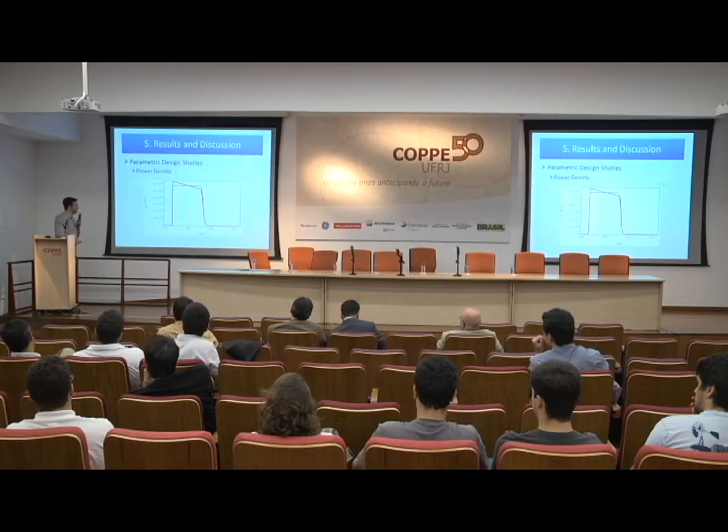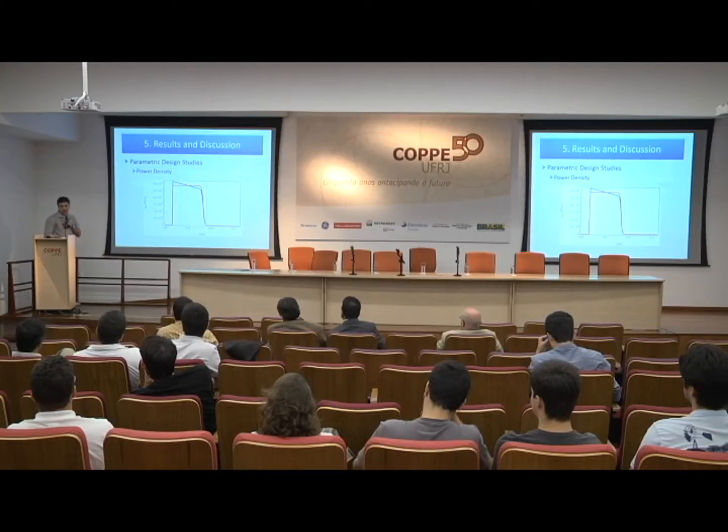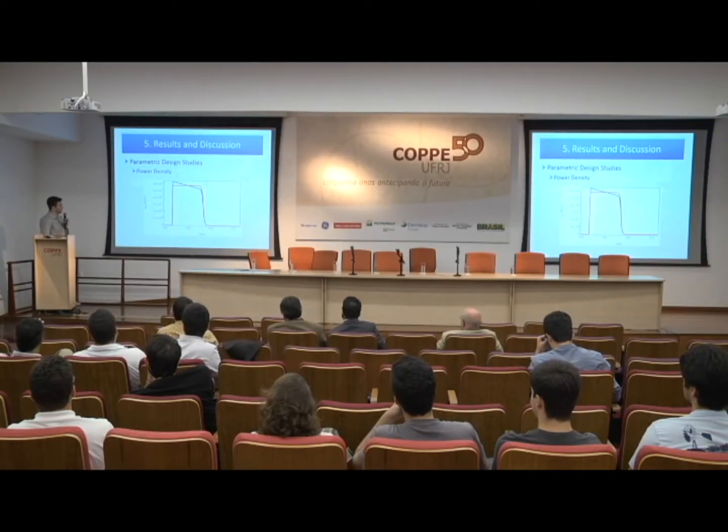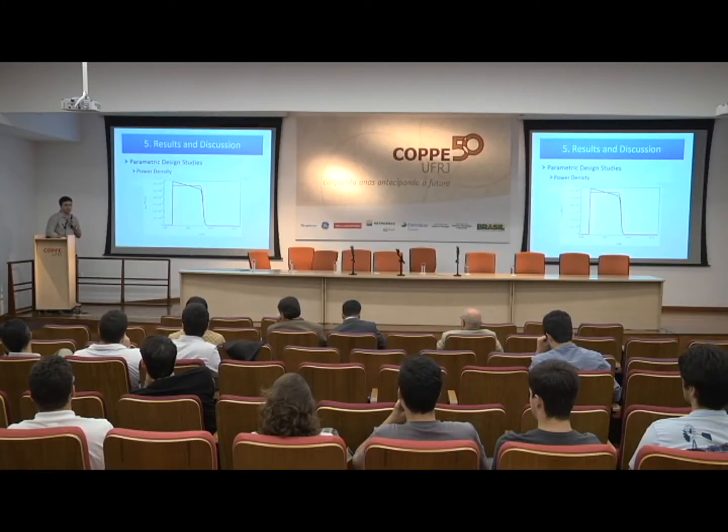And finally, we did some parametric design studies, first with power density. Well, why should the wire give a constant heat generation all over the portion that it resides? Why not give it in a straight line or an exponential? Because we need the heat near the stagnation point. Here, if it's hot or not, we don't care that much. It could lead to ice formation here also.